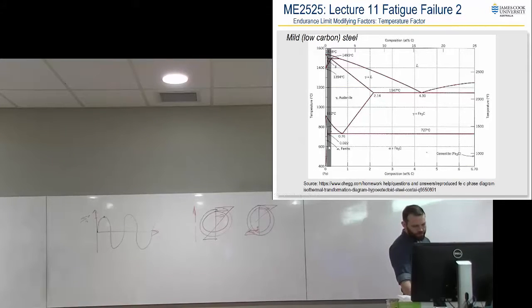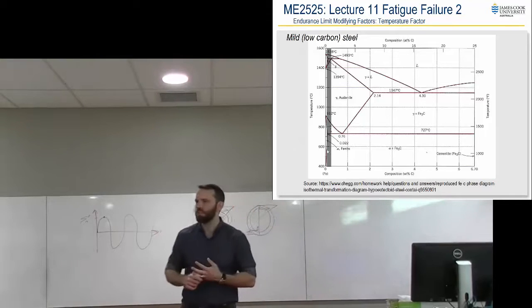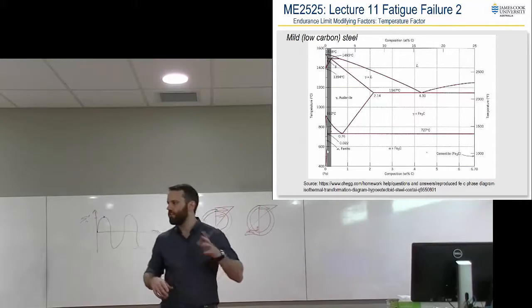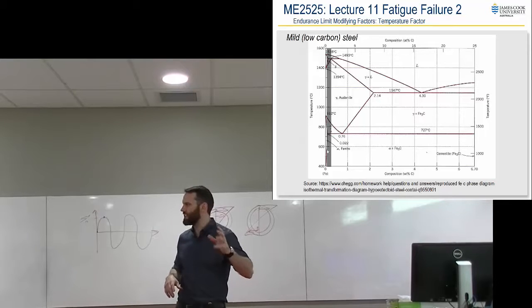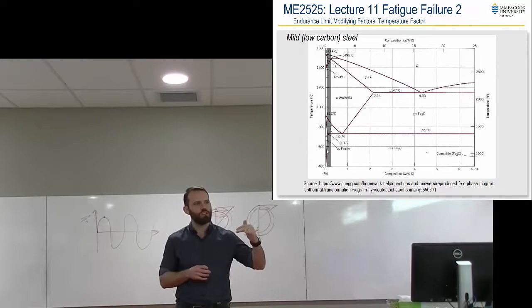At the very low carbon content of mild steel, it's about 550 where that line starts to cross. So just to be safe, that 550 mark is about where we're confident, below which the crystalline structure is still what we need it to be, above which it's anyone's guess.